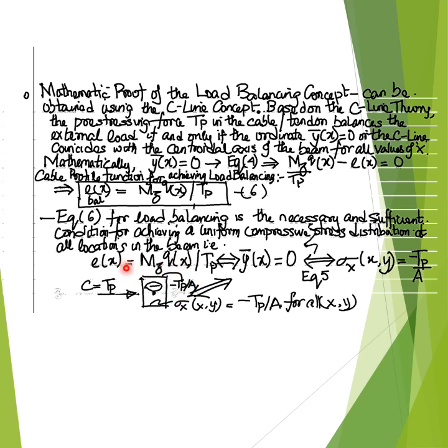thus implying that the pre-stressed concrete beam in which load is balanced, or the mathematical condition for load balancing is fulfilled, is in a state of pure uniform axial compressive stress.